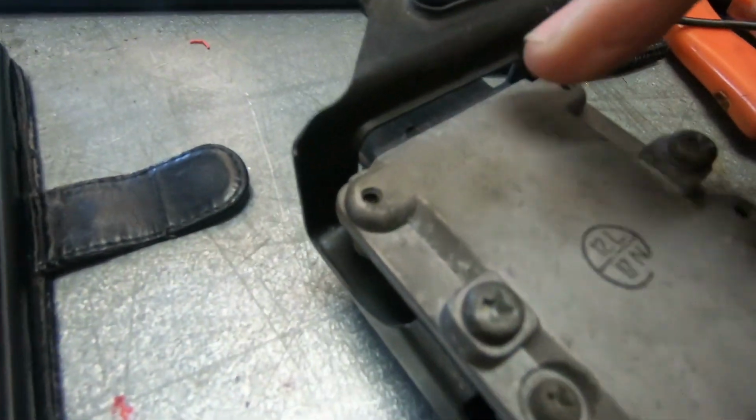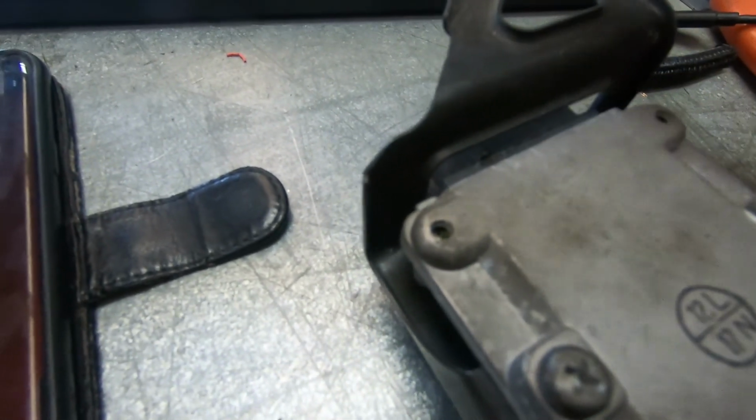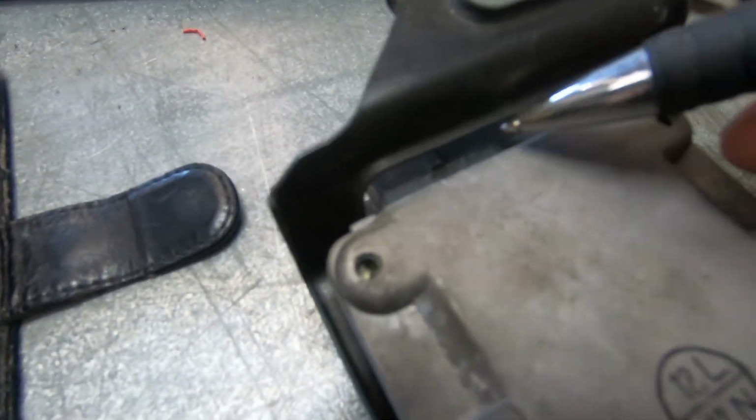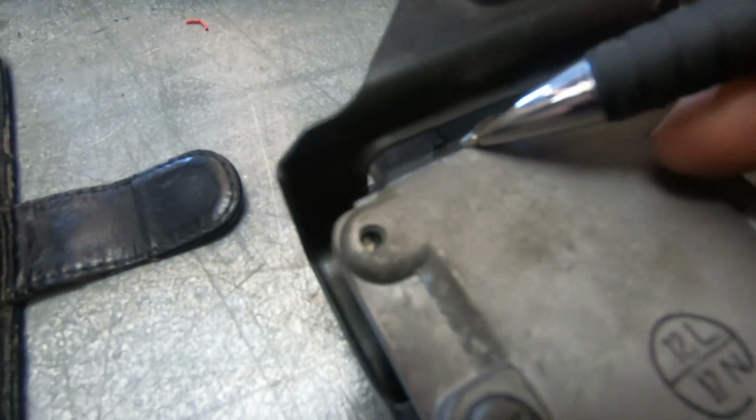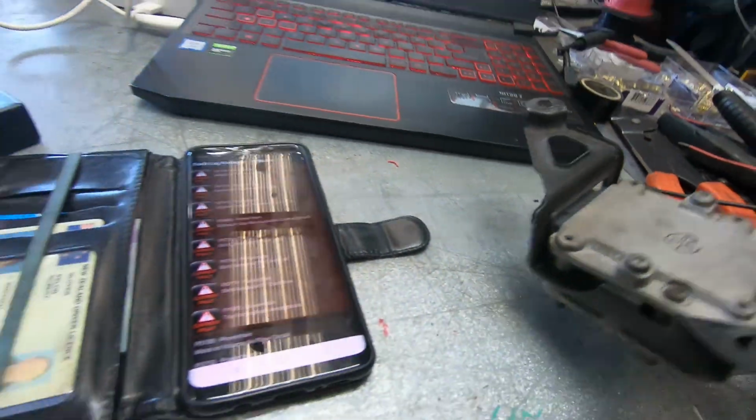And actually on the igniter, what we're talking about here is we've got the pins for the igniter listed under here. We've got battery input, external, which is the tacho, coil input, and feedback. So what the ECU's detected is it hasn't got that feedback for 6 ignition cycles, and it's brought on a fault.